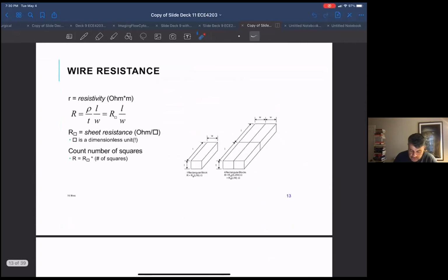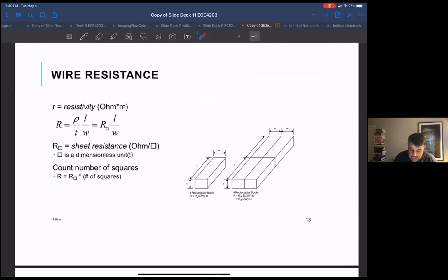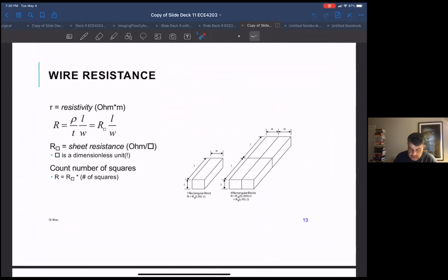Now we're gonna parse through different aspects of the interconnect. So we said interconnects have resistance, capacitance, and inductance. We're gonna ignore inductance. Inductance is really something you only see on chip when you have very long lines that are being driven very fast, or on purpose, when you're building actual inductors on the chip.